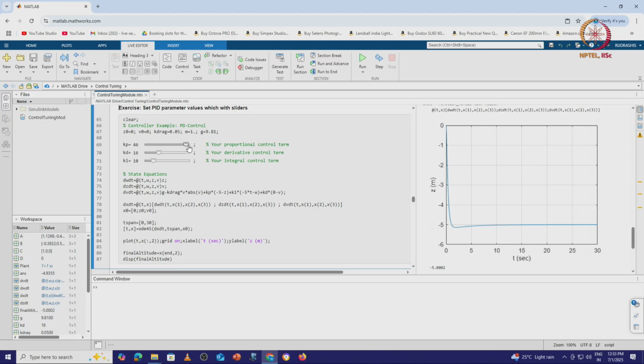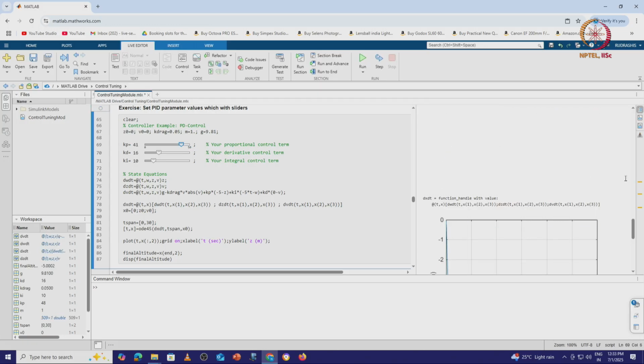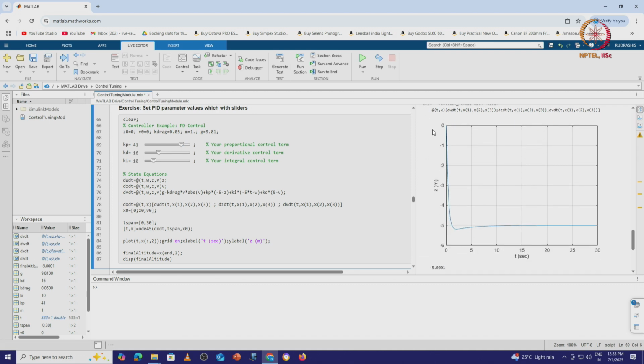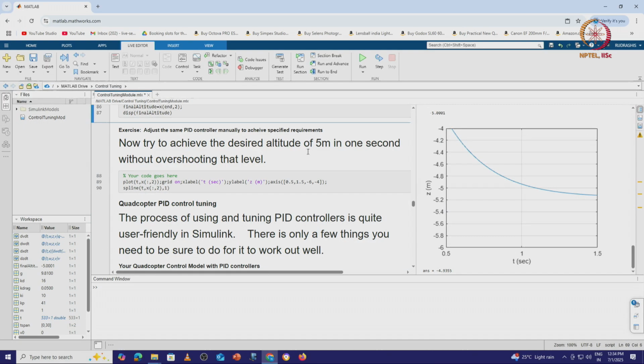But you can change the gain. If you increase or decrease the gain, if I change my proportional gain, right, it just changes the way my response characteristics are going to be. So I can tune my proportional, integral, derivative gains and get proper response characteristics based on the acceleration that is acceptable to me, the response time that is acceptable to me, and I can find those gains here. And using those gains, I can just go and play.